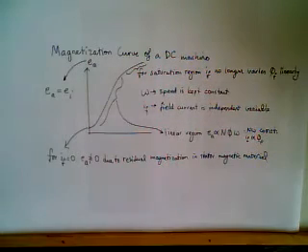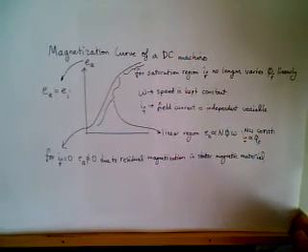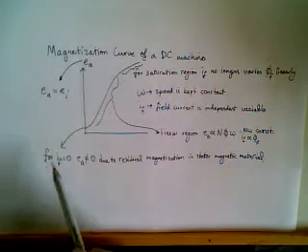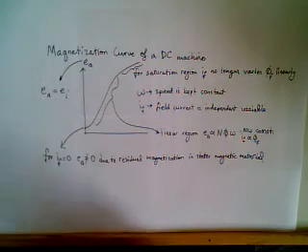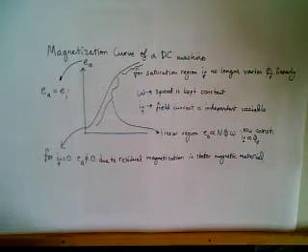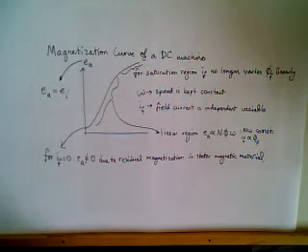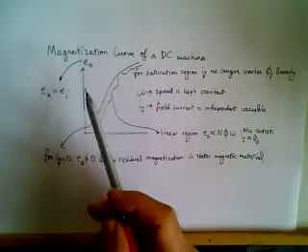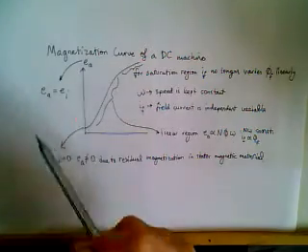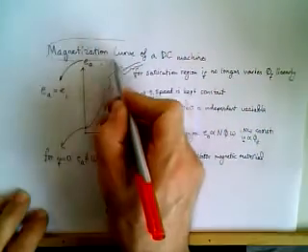tracks of theoretical knowledge. In practice, we cannot express everything with theories. Due to the nonlinear structure of the magnetization curve, there is no analytic solution for different material curves. They have to be done experimentally. So usually experimental and graphical results play an important role to characterize a machine. What we do at that time, we obtain the so-called magnetization curve.